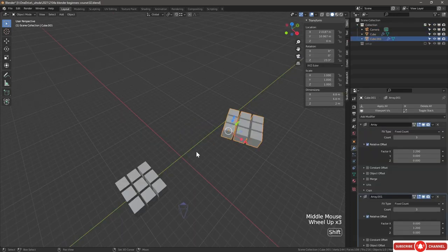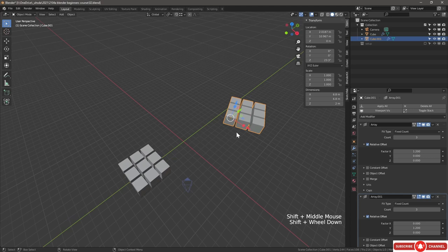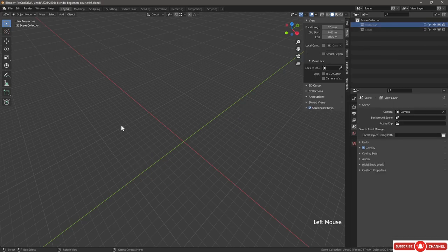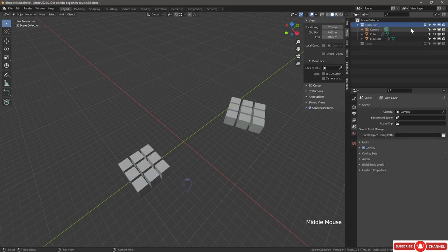In Blender, layers are called collections. Right now we have one collection here. We can uncheck, hide, or disable in the viewport the whole collection. So if we uncheck, everything goes away. To make a new collection, we click this plus icon here in the top right hand corner, and we create a collection. Now if we have one collection active, we have a sub collection that's made within it. We can click and drag it out to move it out.